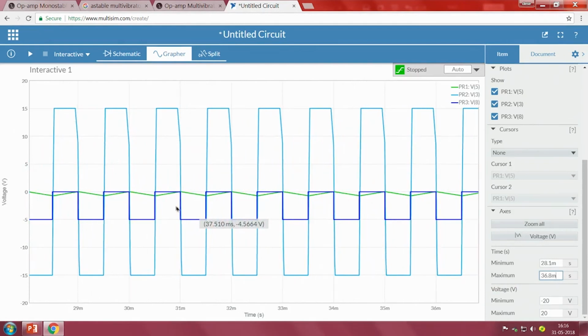So, what is happening? This is nothing but the voltage across the negative pulse that we are giving, and the duty cycle of the pulse is 50%. One thing we can see is that the capacitor is discharging, but not to minus 7.5. While it is ready to discharge, the pulse becomes higher, meaning the pulse goes back to 0. Because of that, again the capacitor starts charging, again starts discharging. So, we cannot expect the result we require.